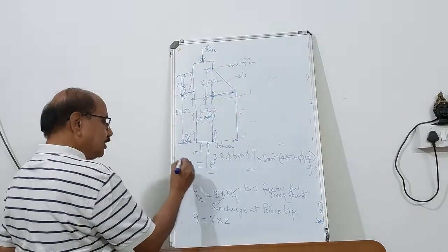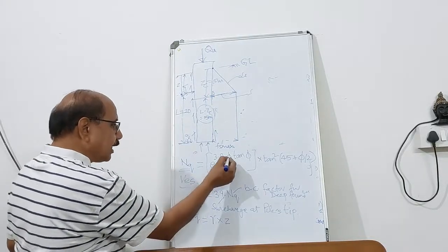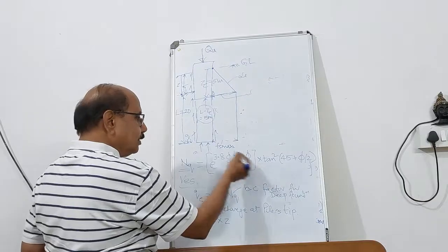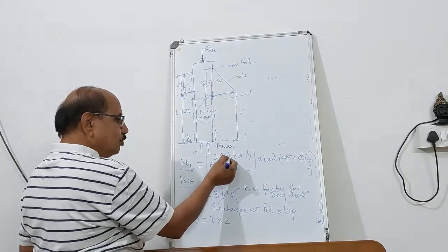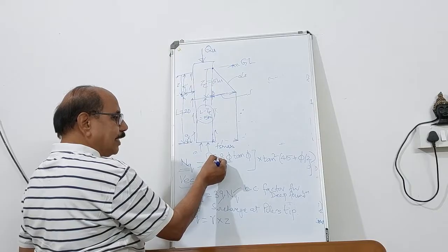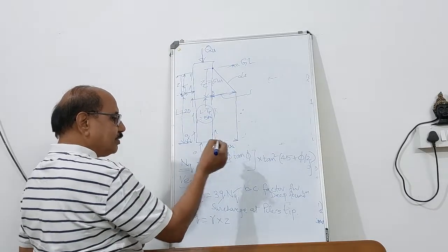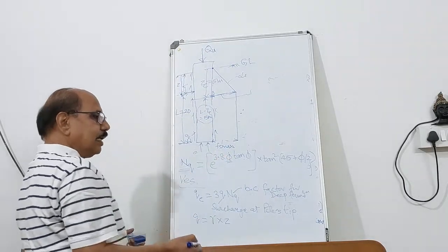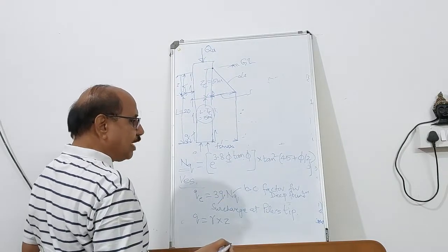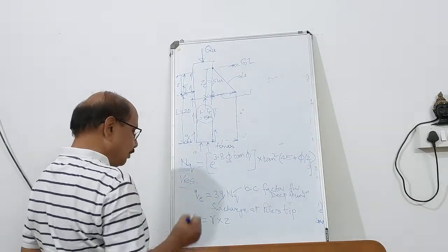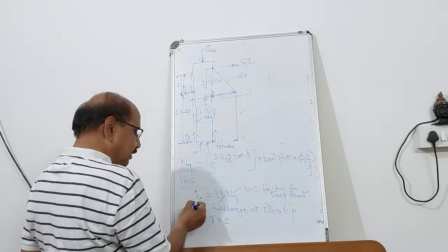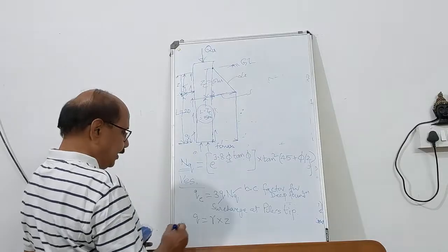So this expression you can calculate. Say phi equal to 30 degree, you can convert it into radian, multiplied by 3.8, multiplied with tan phi, and e raised to that value into tan square (45 plus phi by 2) will give you the value of NQ. Substitute it, substitute the value of surcharge, and you get QE.